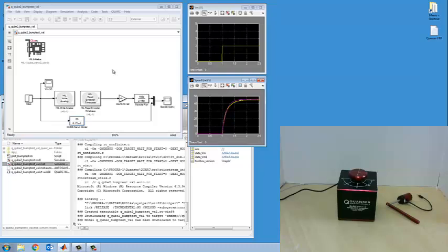For example, if you think of this in an industrial sense, if you had a system like this where the parameters are not known, also known as a black box type system, then you could do this experimental type of modeling to find out what the dynamics are of that system.